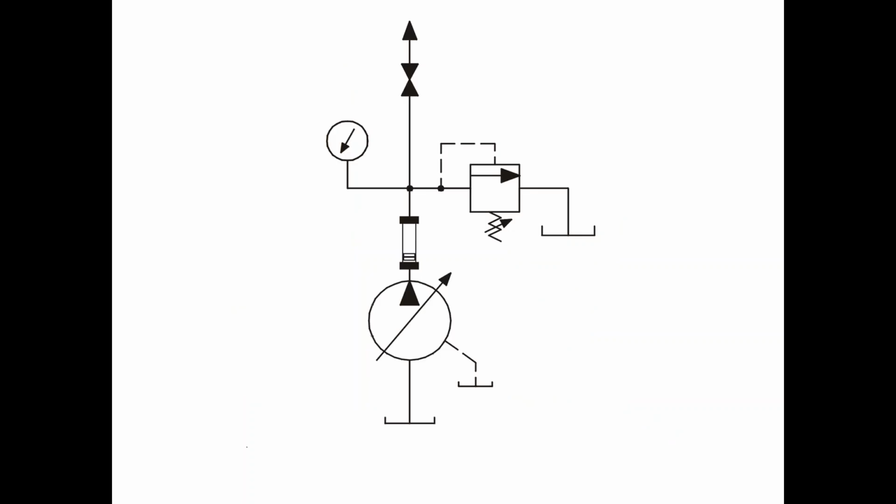Right now, here is the most definitive check of a pump. This will tell you with 100% accuracy, is the pump any good or does it need to be replaced? Right, you see we're using a fixed displacement pump, and we've closed this hand valve, blocking the flow so that the only way for oil to go is across the relief valve. Now, we've installed a flow meter in the pressure line here, so that anything that dumps across this relief valve goes through the flow meter.